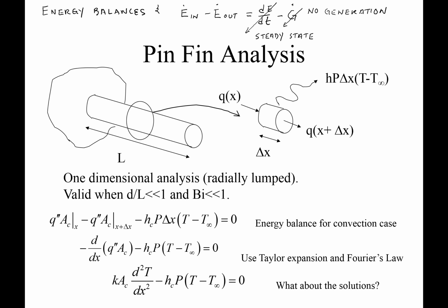Now, for this fin, the cylindrical fin of length L that we're seeing right here, we extract from it a differential thickness element. So by differential element thickness, we're saying that there is some delta X thick element in this fin that we're going to consider and analyze. We expand to look at it, and we recognize that there's conduction in at the location X.